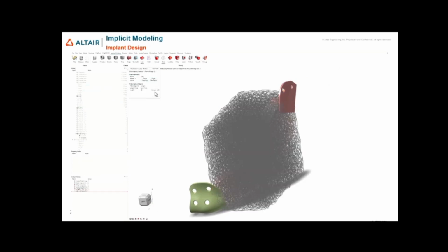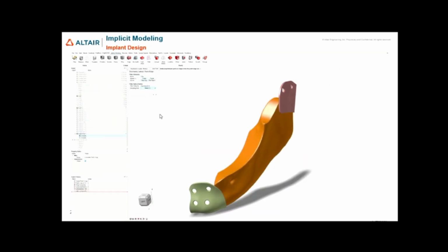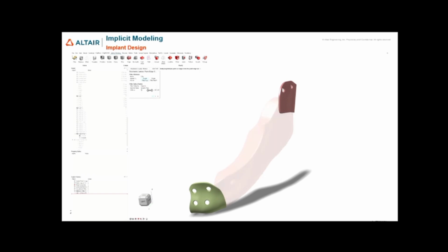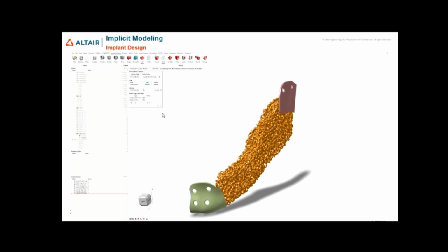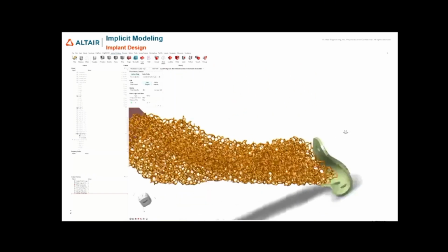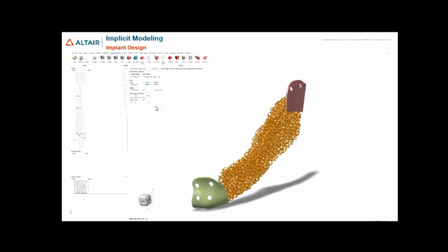We can then fill the entire bounding box and connect them up using a Voronoi structure. Then we can use some filters to ensure that the beams only live inside the volume that we want. We can also apply a valence filter to stop any single, floating edges sitting on the side. We can then create that and choose our lattice thickness.